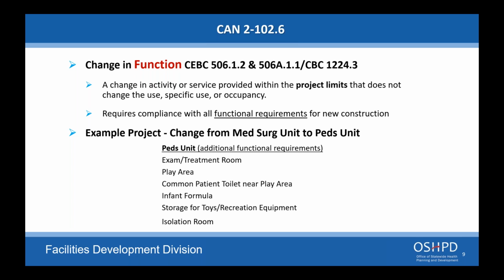Yeah, you can use the ICU rooms as ED bays, but you're going to have to look at the clearances required for the ED. Again, you have to meet the functional requirements of the new use. So a new emergency department is going to have clearance requirements for each bed position, for each bay. It's going to have nurse station requirements. All those things need to be identified and applied. And you have to show that you comply with the clearance requirements or space requirements, size requirements, et cetera, for those spaces.